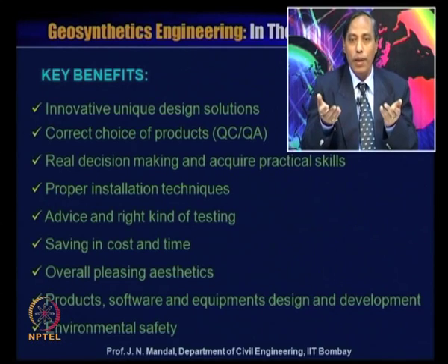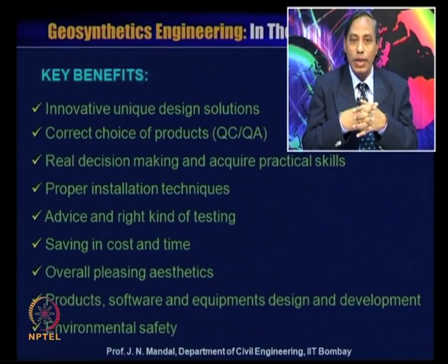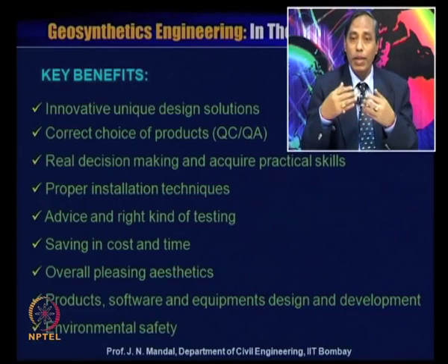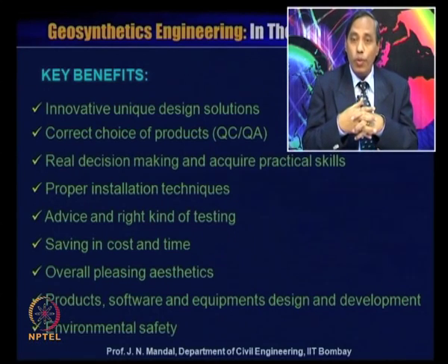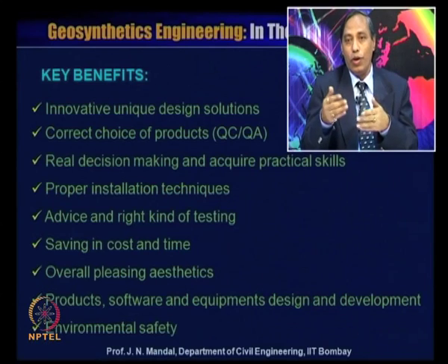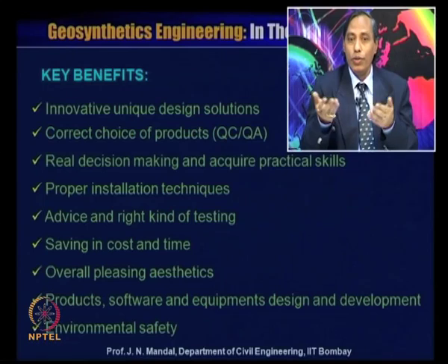So, you can benefit by learning about the testing of the material and what kind of tests are to be conducted. There may be different defined types of tensile strength for geosynthetic materials. So, one has to be careful about which one should be recommended for this particular application. If you do, you can save both cost and time.